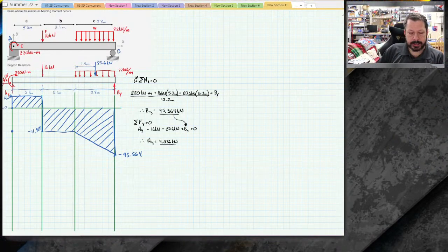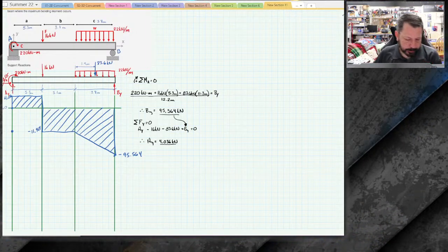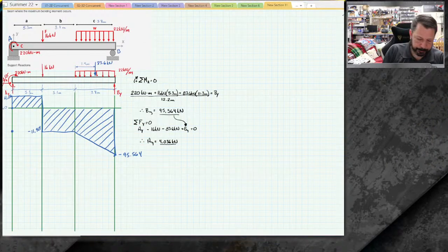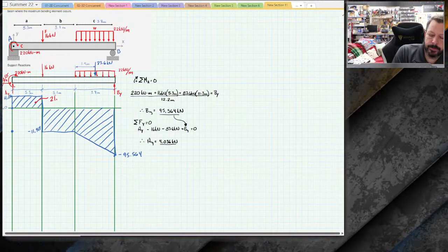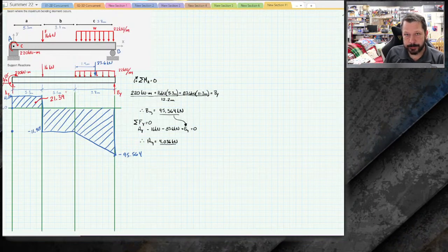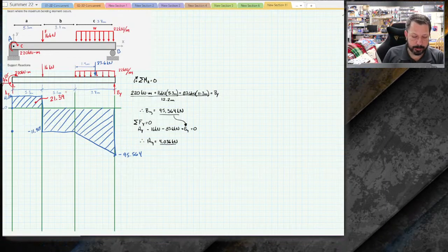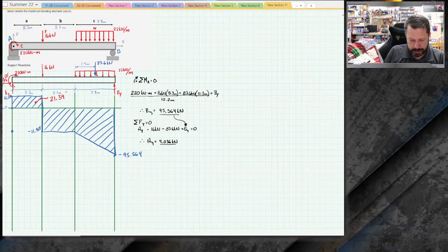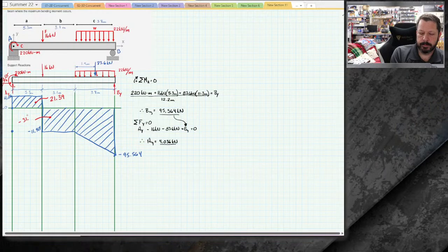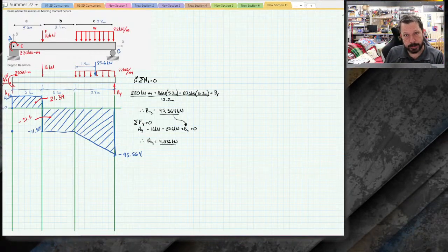Okay. Now what we need to do is integrate this, which means calculate the area under the curve, so it means add up all these little areas. So the first one is 4.036 high times 5.3 meters wide. So this is 21.39, and I'm rounding now. The shear diagram started and ended exactly at 0. The moment diagram, if I'm going to round here, is not going to end exactly at 0. I want it to be close to 0. If it's not, then I possibly made some error somewhere. The next rectangle, 11.964 times 3.1. This guy is negative area, negative 37.1, I'm going to call it. And these units, if you look at them, the height of this rectangle is in kilonewtons. The width of it is in meters, so kilonewton meters, that's a moment.